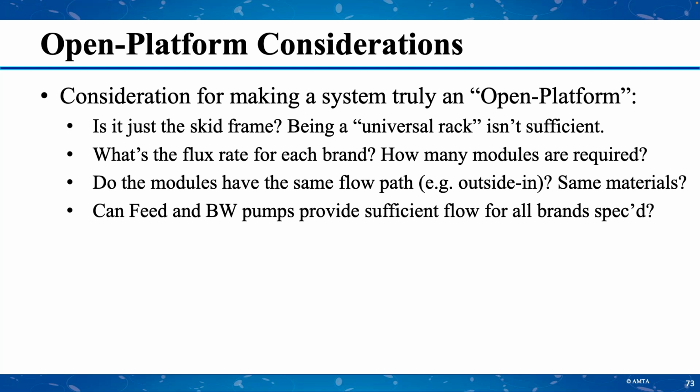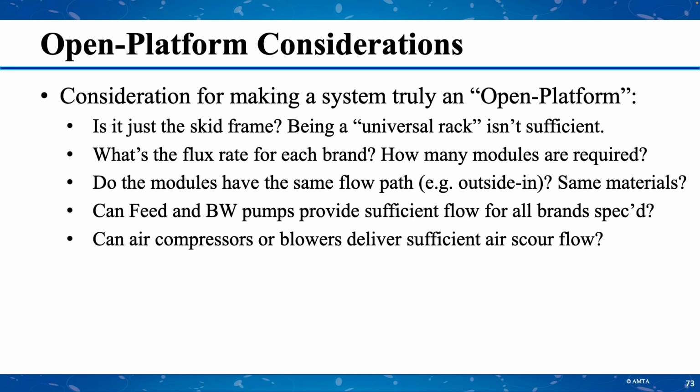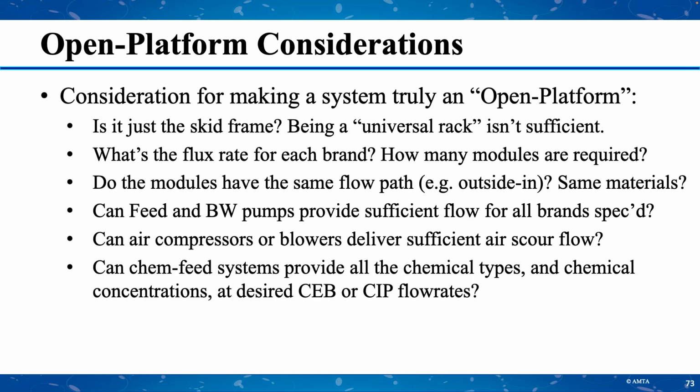Can our feed and backwash pumps provide sufficient flow for all brands? Is cross flow required? Can air compressors or blowers deliver sufficient air scour flow rates? Can the chem feed systems provide all the chemical types and concentrations at the desired cleaning flow rates?